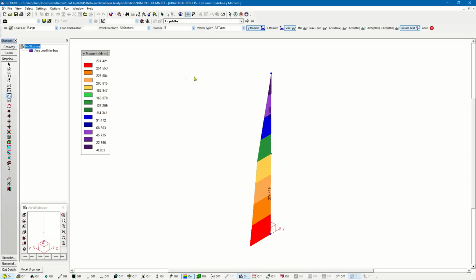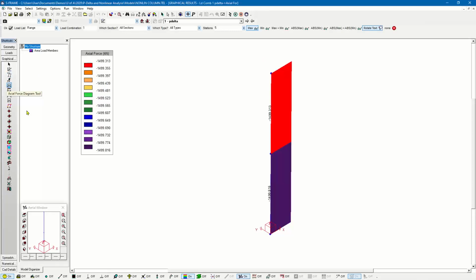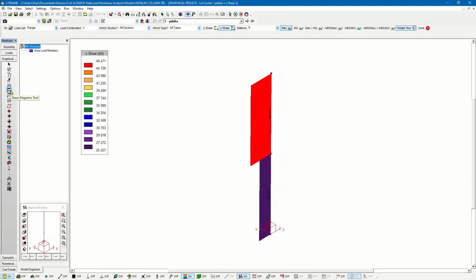In this situation, we probably need to really break down the analysis results to get an understanding for what's going on, but we're getting about 150 millimeters of displacement. And so what we're getting here is slightly lower axial loads because some of the deflection is inducing some lateral forces into the model, as this eccentric joint at the top is still being loaded in the vertical direction. The deflection or the angle of that member is going to lead to some lateral forces or some shear forces also being generated, as you can see here.